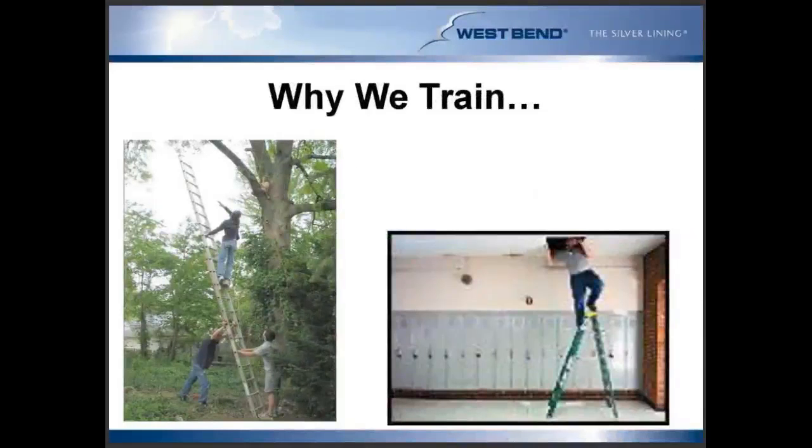The last one here to the left that I really like is it looks like they actually do have the proper angle for this extension ladder, because the employee at the bottom to the right is holding it and has his arms, it looks to be, at a 90-degree angle with his feet up against the feet of the ladder. So that typically is a good gauge for making sure we have that 4-to-1 ratio that we need. But what I really like about this is the employee on the back side of that ladder bracing it for the employee that's actually on the ladder.